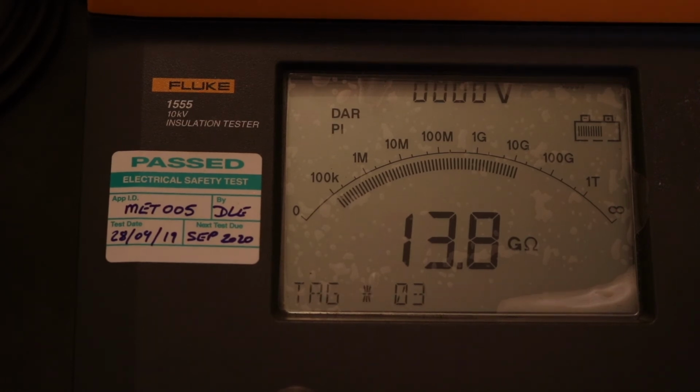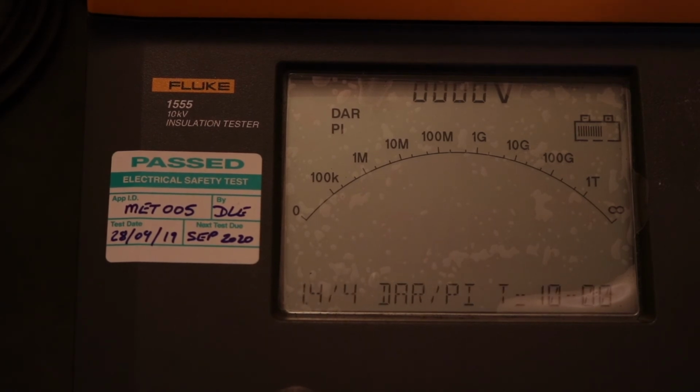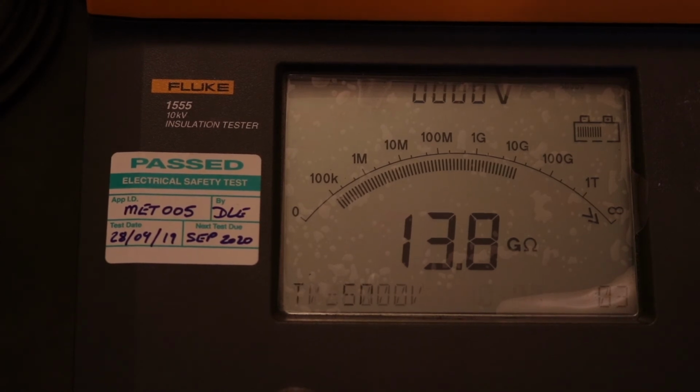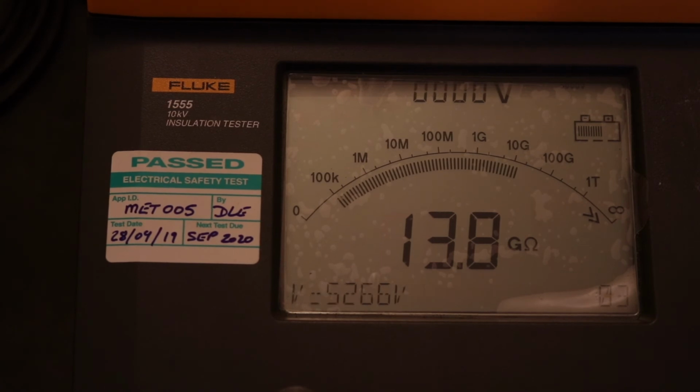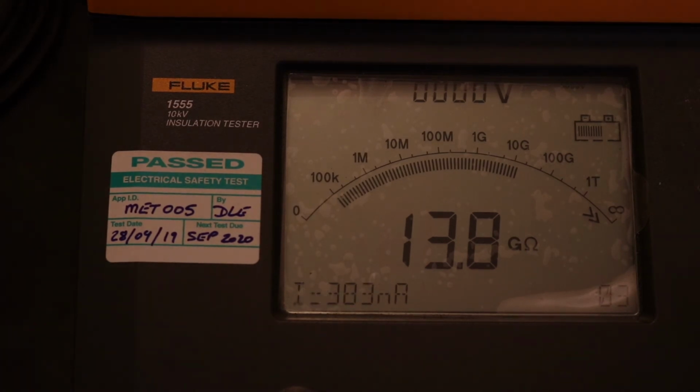I will store this. It gives me a tag name then, and what I can actually do is show those results. Tag 1, there's tag 3, there's my result there, and then I can then page through relevant readings. Gives me an initial setup. There's the test voltage was 5266 volts, capacitance it didn't find anything, PI was 6.28. It does, at the same time as it does PI, it does do the DAR as well, which is a very nice feature. And then it gives me the current, that'll be at 10 minutes.